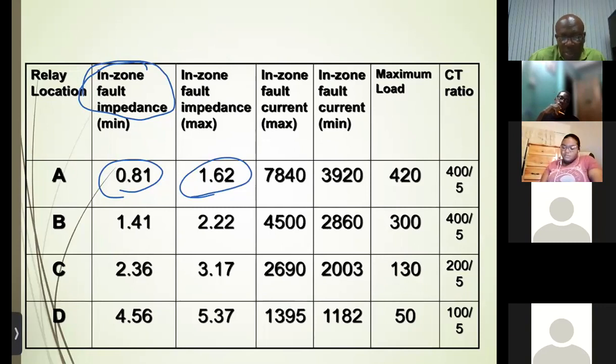With a 1.62, that's with one transformer in, so it would now be 11 squared over 75. But we don't really need to work that out because we know this is at 150. So at 75, then it must double. So we get 1.62.